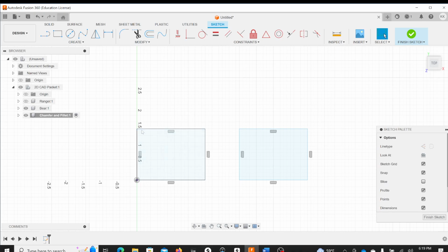On this first one, we're going to chamfer the edges, which means we are going to create a line that bridges the gap between this edge or this line and this line here. So we will get a line that looks something like that when we are done. Now notice I drew that at a 45-degree angle, and 45-degree angles are what we are going to make.